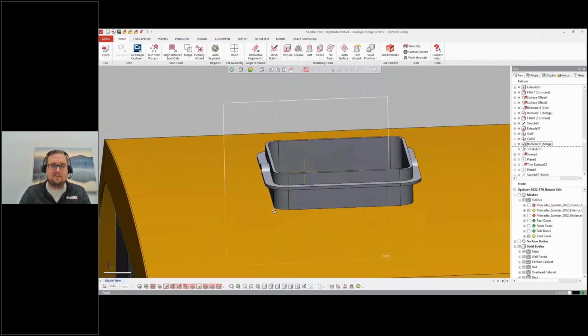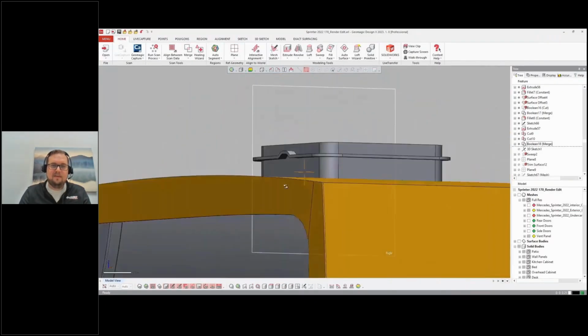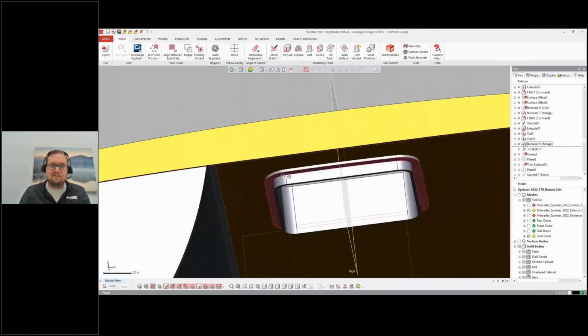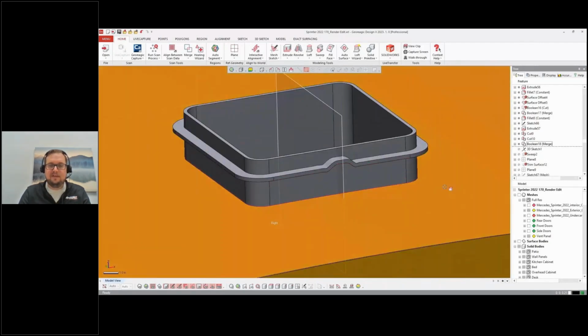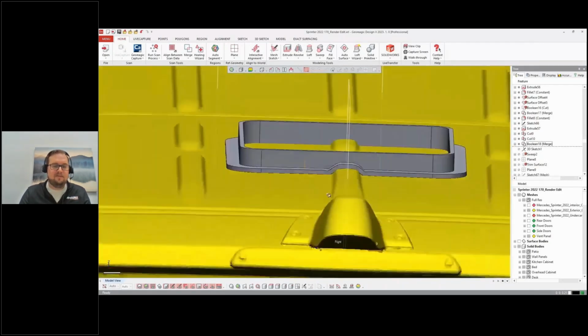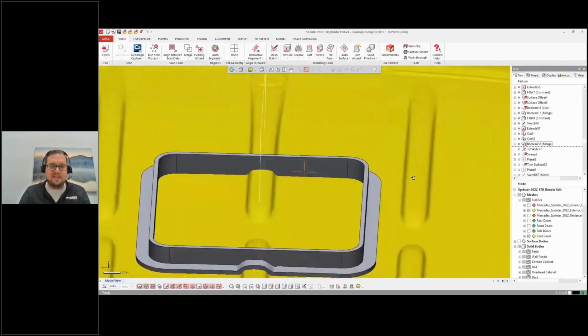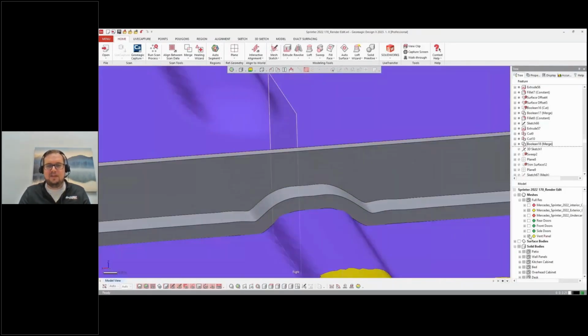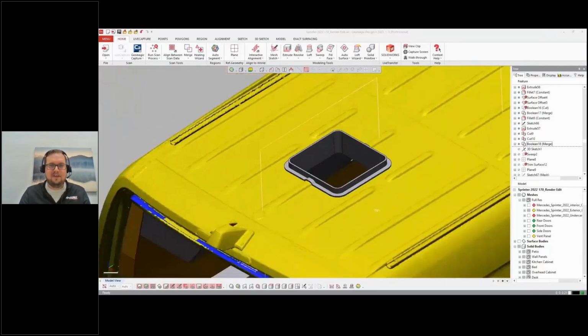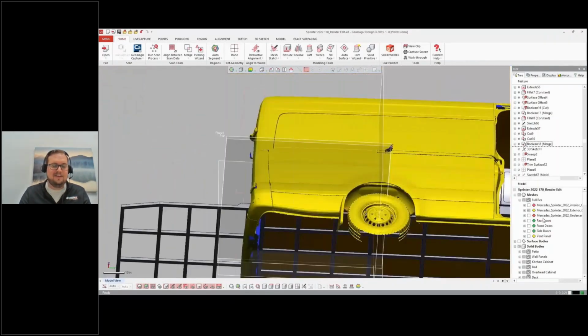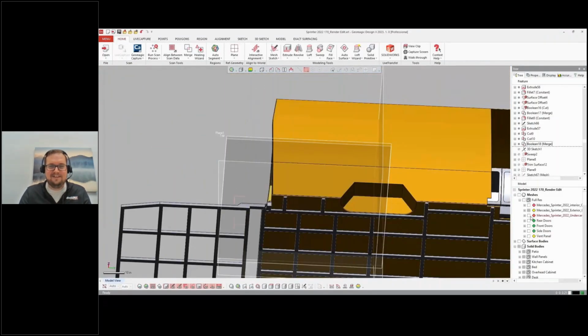So you can see there's our gap for our insulation there. And we match the curvature both inside right here, as well as our seam along the top. We could seal that now with silicone or a foam tape, rather than relying on something like an expanding foam that's likely going to leak over the years, or even just globbing on to make a gasket to make that seal.